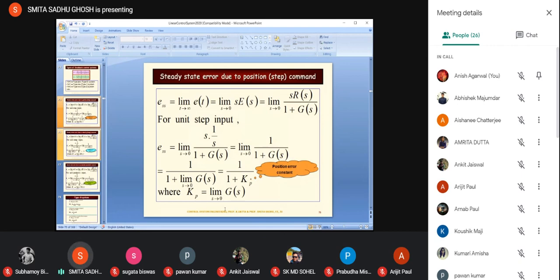Rather, we are going to assume that given stable systems, if we are to calculate steady state error, we would have to use the methods that we are outlining. That is the least we can say right now. Say for example, if you are speaking of an unstable system, the response itself is going to be divergent and become very large. So calculation of the steady state error would become irrelevant in such cases.